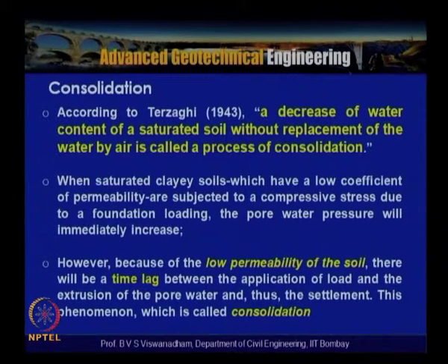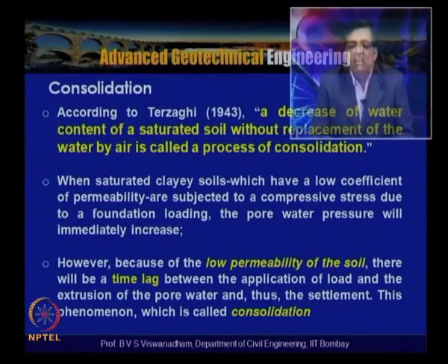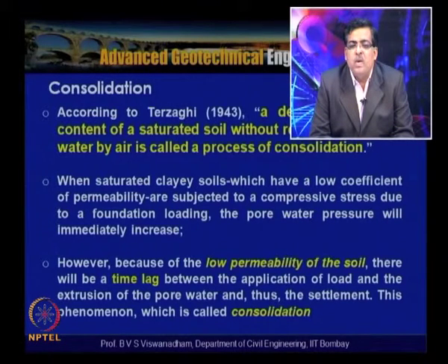When a saturated soil with a low coefficient of permeability is subjected to compressive stresses due to foundation loading or any structure loading, the pore water pressures will immediately increase. Then it takes some time for the pore water pressure to dissipate. Because of the low permeability of the soil, particularly a fine grained soil like clay, there will be a time lag between the application of the load and the expulsion of pore water, and thus the settlement.